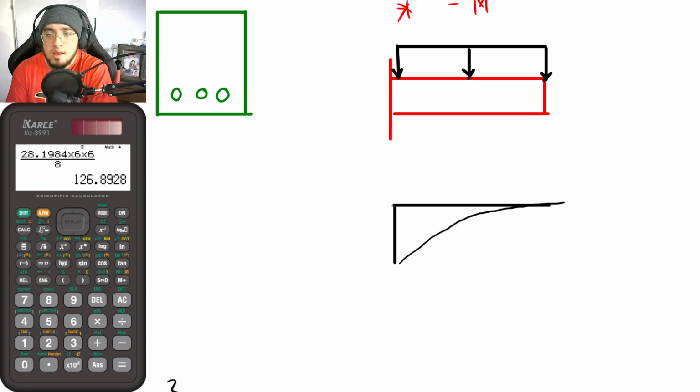And as you can see, that instead of having a positive moment, we now have a negative moment. And if it is a negative moment, as you can see guys, for this particular sample, its manner of bending, since it is negative, emulates a sad face. Or it would now sag like this. So this is now its manner of bending. Okay?